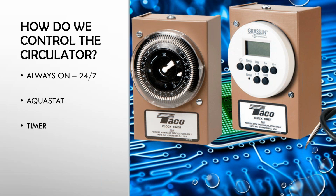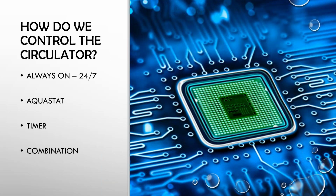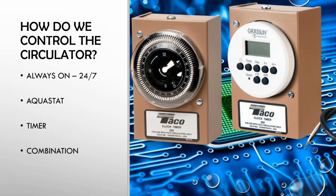The next option for controlling your circulator is a combination of the timer and the aquastat. So now you can use an aquastat in conjunction with the timer to keep the circulator off more than on. That's the idea. We want to keep that circulator off as long as we can, but also make sure that the water's warm, and also when we need it to be running. So you can do a combination of the two.